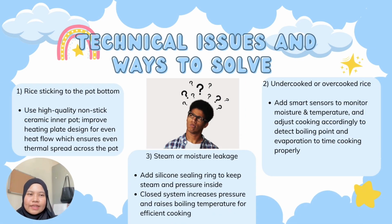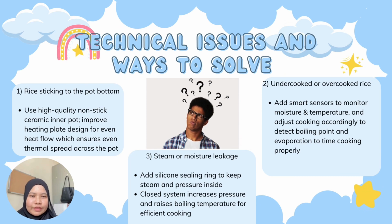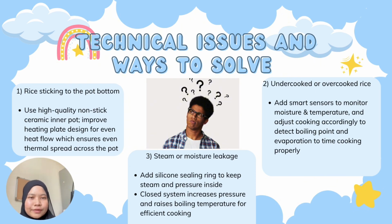So, these are the technical issues and ways to solve them. First, rice sticking to the pot bottom. We can use a high-quality non-stick ceramic inner pot and an improved heating plate design for even heat flow, which ensures even thermal spread across the pot. Second, undercooked or overcooked rice. We can add a smart sensor to monitor moisture and temperature and adjust cooking accordingly, to detect boiling point and evaporation to time cooking properly. For steam and moisture leakage, we can add a silicone sealing ring to keep steam and pressure inside. This is because a closed system increases pressure and raises boiling temperature for efficient cooking.